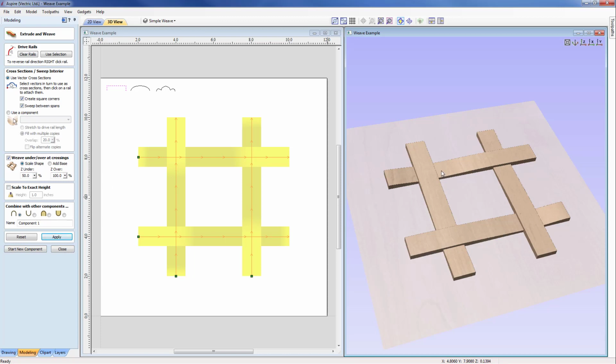in these areas. Now as well as that, if I put this back to 100%, you'll see that we get this back as it was before, and now we're going to look at the over. So the over is going to be increased to 150. So essentially what we are doing there is increasing the region when it's passing over to be another 50% higher than what it was originally.